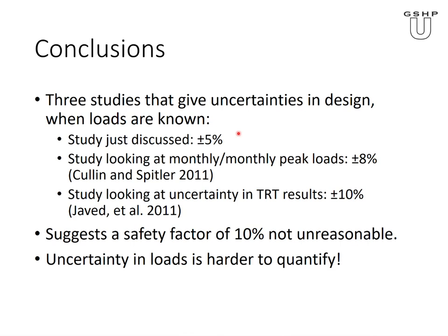So that's another possible reason for suggesting some safety factor. The flip side of that is that ground heat exchangers tend to be fairly stable, and usually when we choose a design entering fluid temperature, it's not the case that the system fails if we exceed it by a degree. So all these things go together in maybe deciding on a final safety factor.